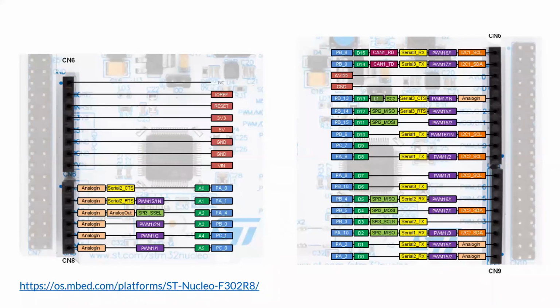Finally, I just want to show this slide here. This is to show that all of the peripherals and controllers inside the microcontroller are each connected to maybe 1 or 2 input and output pins on the device. So when you're working with hardware and software integration, you need to be aware that you can't connect an analog to digital converter pin to any pin on your device. One analog to digital converter inside your device may only connect to 1 pin on your chip.